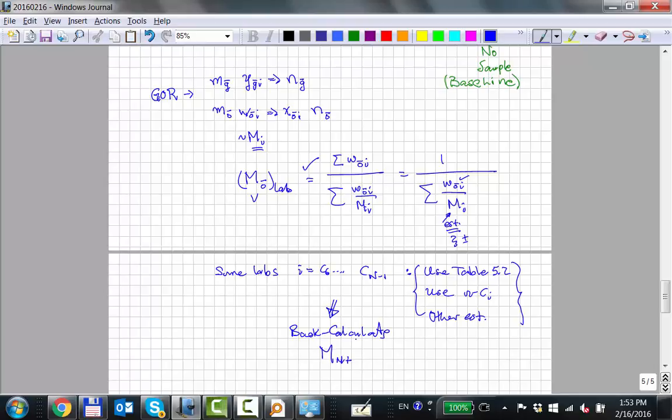The problem is if you use Katz-Firoozabadi in a case where it should be something more like normal paraffins, the C31 plus molecular weight is going to be crazy. It's going to be ridiculously high or low, I don't know. Okay?